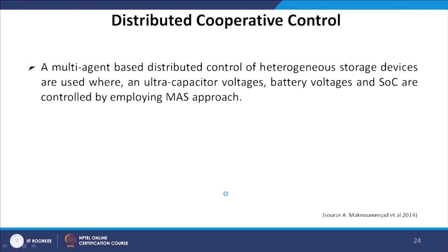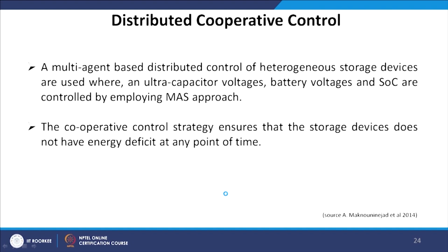Distributed cooperative control. A multi-agent based distributed control of heterogeneous storage devices is used, where an ultracapacitor voltage, battery voltage and SOC are controlled by employing a mesh approach. The cooperative control strategy ensures that the storage device does not have an energy deficit at any point of time.